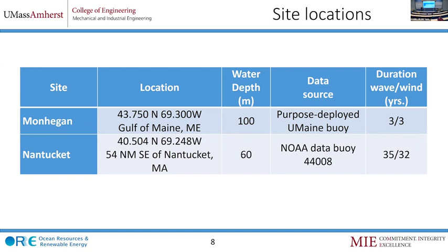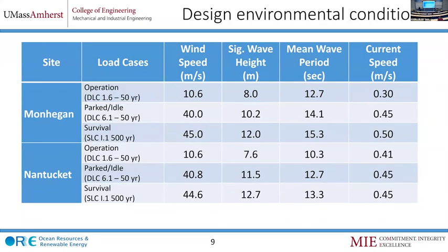The water depth where the buoy is, is around 75 meters, 74 to be precise. But we chose a water depth nearby, about 60 meters, because we want to study how we can design a mooring system for 60 meters. As you know, 60 is very shallow for moorings. Based on the buoy data, we were able to get the environmental parameters: